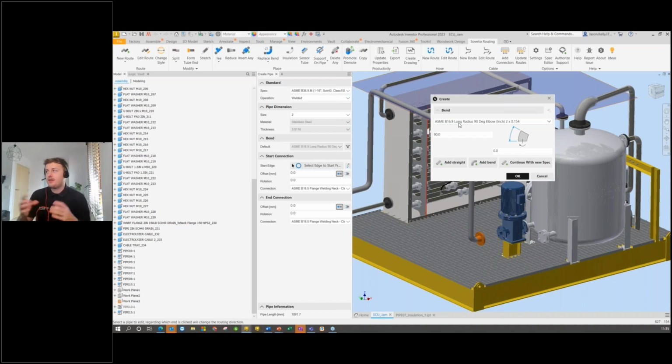Yeah, definitely. I think both of the tools do have that kind of self-draining option, or the self-draining tool available. They just work in slightly different ways. That's really easy. It's a one-off setup, and then once you've got a custom elbow, you can model in any fall for any system then. Yeah, exactly. Once you've got that set up in the spec, then you're just choosing that particular angle.